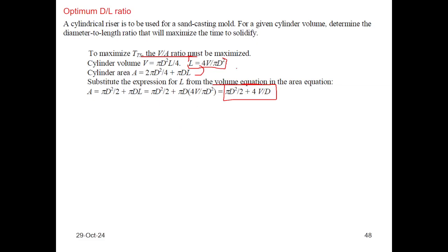And then, to make the mold constant, to make the solidification time maximum, we know that the volume to area ratio is to be maximum.